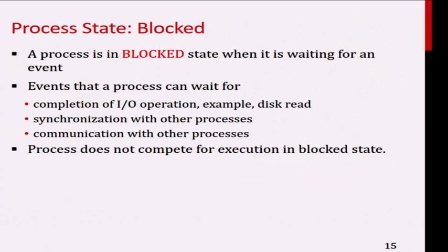The other state is called the block state. In some books, they call it the pending state. It's the same idea. When do you say you are in a pending state? When you have to wait for something. For example, you may be waiting for some data to come in on the serial port. If the data never comes, I have nothing to do, so it's a block state. Or I'm waiting to synchronize with other processes, meaning I'm waiting for task 5 to send me some message, and if task 5 hasn't sent it, I wait. Or I want to communicate with other processes, and I want to send some information over, so I wait first.